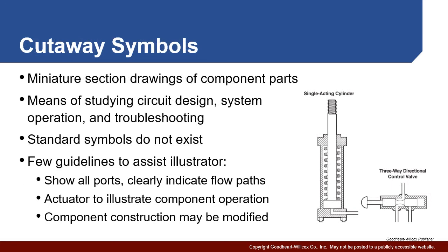Now, cutaway symbols actually show the inside of the device. So we're back to that same two components, this single acting cylinder over here and this three-way directional control valve over here, but now they've been sliced open. And what they're designed to do is show how the system functions on the inside and hopefully assist in things like troubleshooting, where you could find a way or be able to tell what potentially could go wrong.